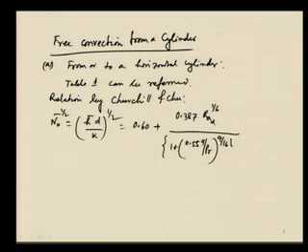So, this looks a little complicated, but these are relations which are very commonly used if somebody has to find out the values of the heat transfer coefficient for such a situation. And here the range is 10 to the power minus 5 less than Rayleigh based on diameter less than 10 to the power 12. This is one condition. So this covers a wide range.